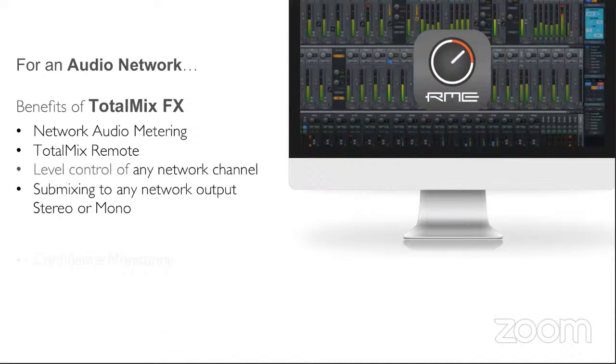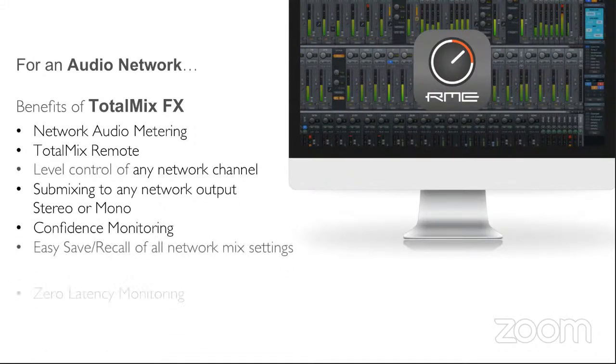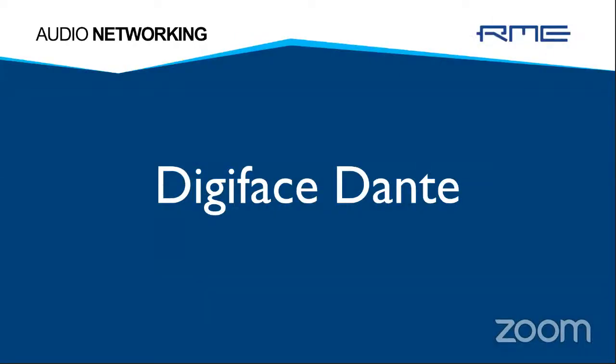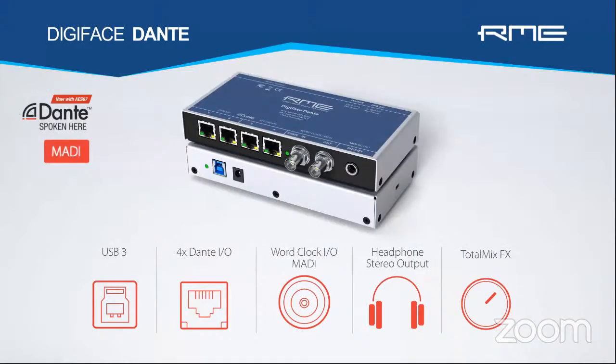So the benefits of Total Mix for an audio network are metering and remote control and level control, submixing, confidence monitoring, all of these things that we just covered. Now, those features are common to both the AVB and the Dante version. However, the Digiface Dante is a little unique because it not only does Dante, it does MADI. So it has BNC MADI as well as Cat5 Dante.